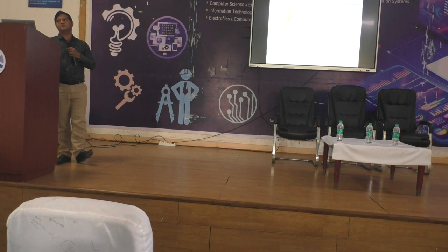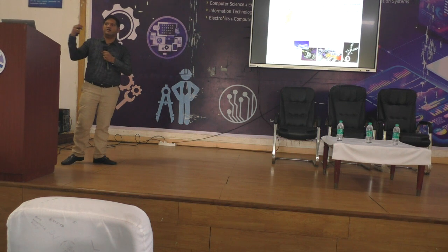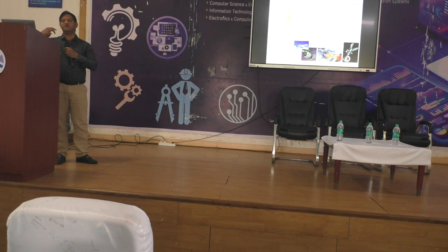And region 4, that is the mass complexity. So the same example that we used, this is the aeroplane engine. This is where the injector is placed. Here 19 components are reduced to one monolithic component by using additive manufacturing. And here, it's not that we want 1 or 2 numbers. The aerospace industry requires around 40,000 injectors per year. That means the volume is high, and at the same time the complexity is high. Such components fall under region 4, that is the mass complexity.